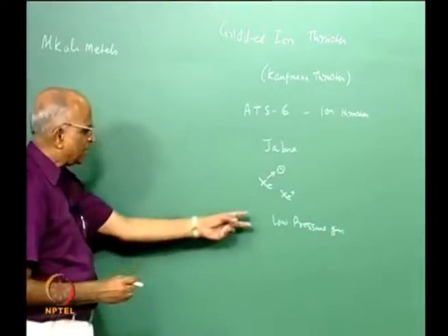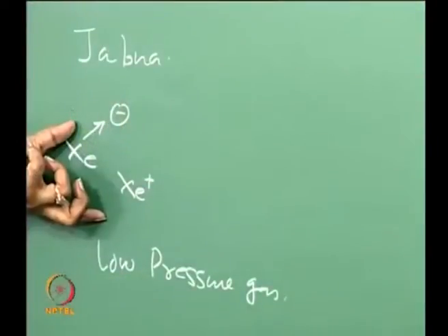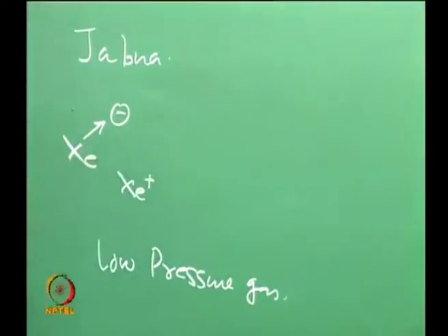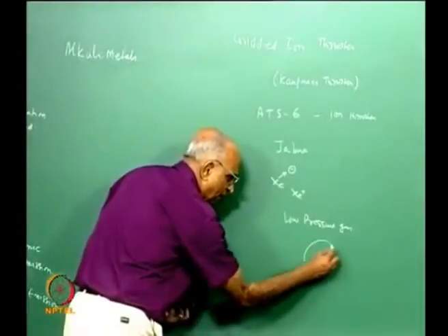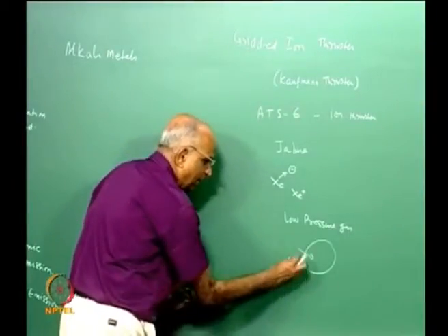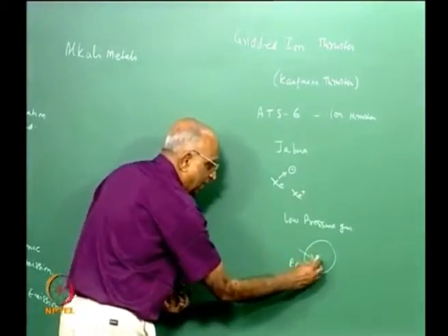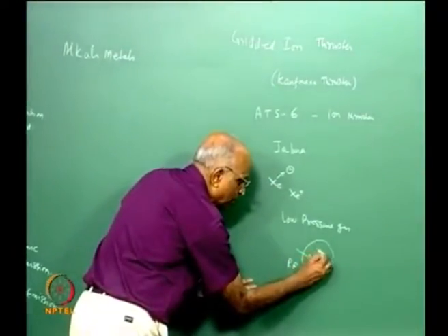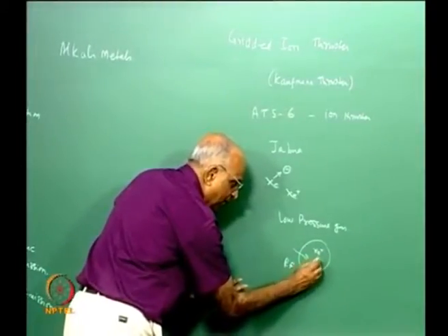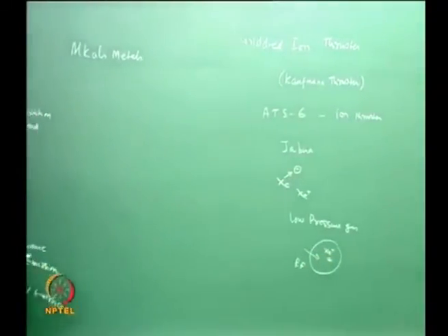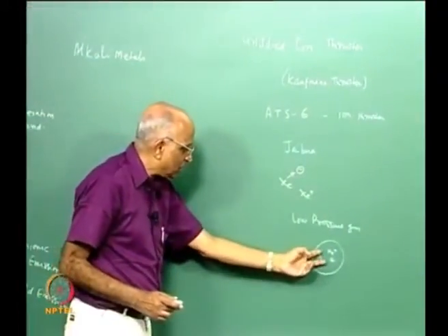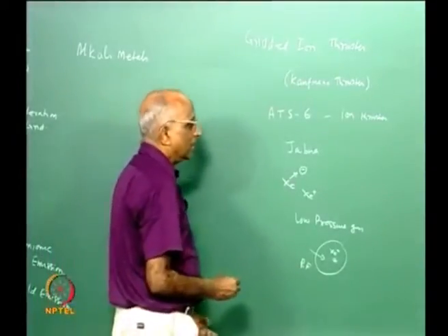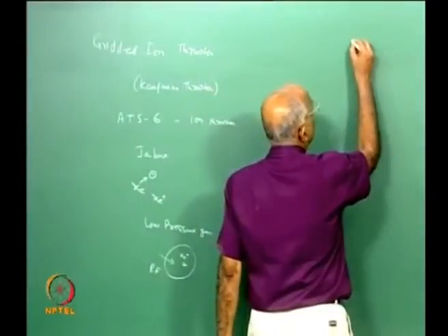and into this low pressure gas, supposing I were to heat the gas. And how do I heat the gas? I oscillate something, like I put radio frequencies in it. I have a volume of gas, I put radio frequency into it, I excite the gas and heat it, and in that case when I heat it, gases like xenon tend to form positive ions and negative electrons, and I use the same attractive forces. In other words, I use radio frequencies also to generate positive charges, and if I use radio frequency, well, the thruster is known as a radio frequency ion thruster.